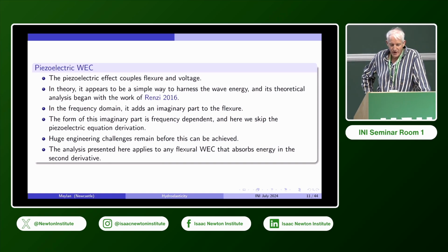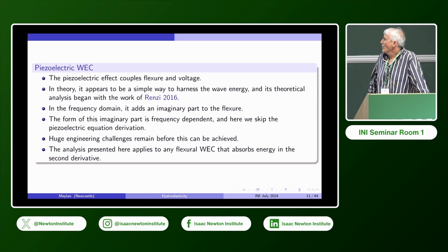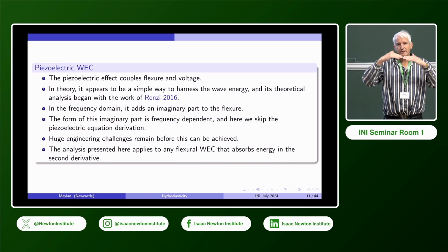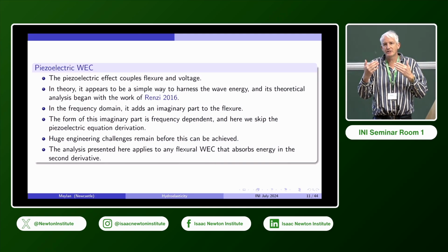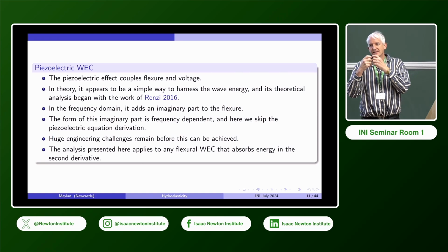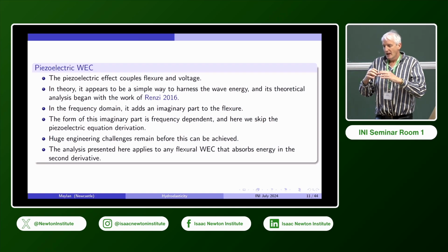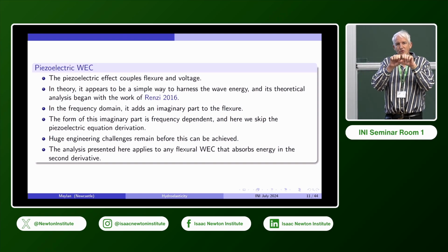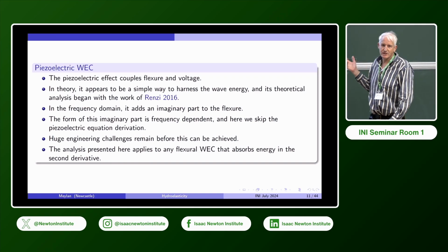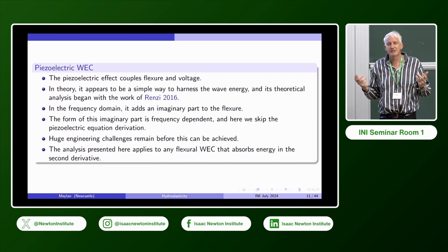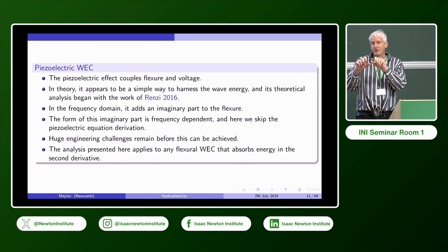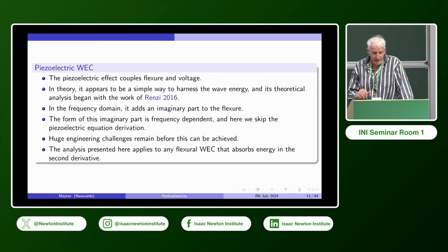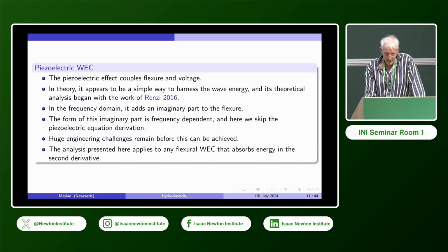One of the things that's important to note, I think, in all of the work that follows, is that if you have a material, if I move it, and I give it a first derivative, I don't put any energy into it. But if I put a second derivative, if I bend it, I put energy into the material. And if you design some kind of wave energy conversion using flexure and you're removing energy proportional to the second derivative, all of this analysis will apply. So it could be some other mechanism than piezoelectric. For example, it could be some way that you're forcing the fluid to move as it bends or something like that. So it's anything that absorbs energy in the second derivative. So from bending, this will apply.